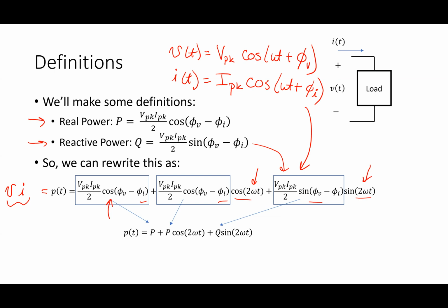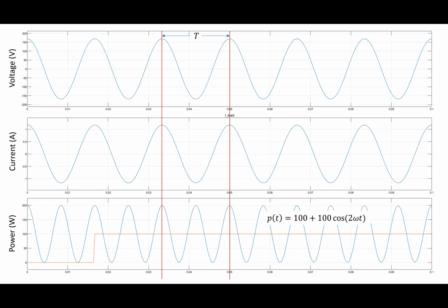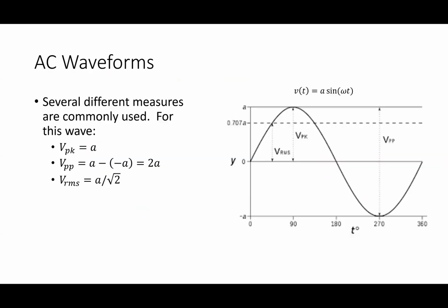And then Q, what is this Q? Reactive power. What's reactive power? It relates to what's going on with the storage in the system. If Q is 0, there's no storage, right? It's only doing energy conversion. What does my load need to have for there to be Q? It has to have an inductor or capacitor. There needs to be something with storage. Okay, you can look at these examples again to talk about that.